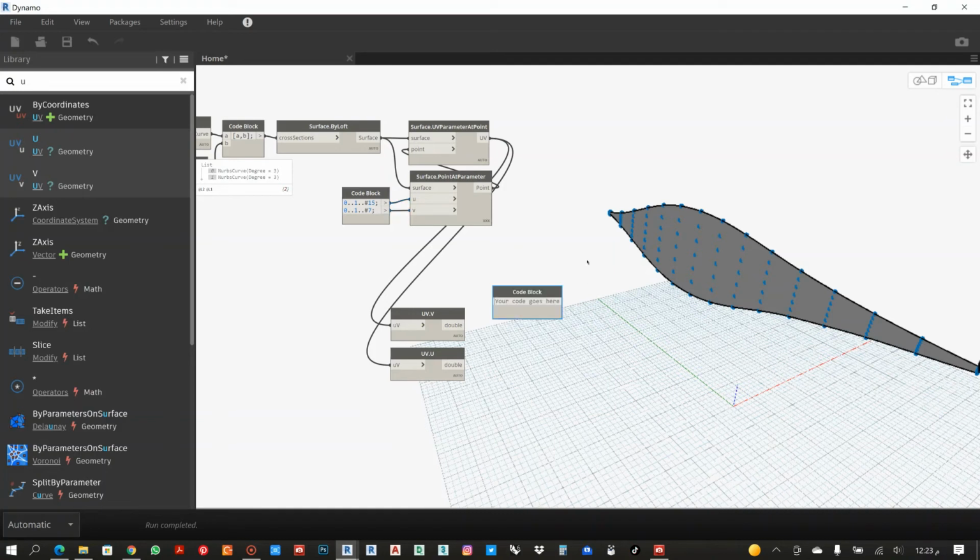My equation for this surface, let's say I need to make my curve in the z value. So the z value regarding this surface should be made by u and v sine multiplied by 180. So the values from 0 to 1 will start to increase and make the curve regarding my math equation.